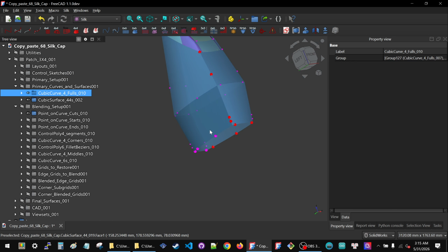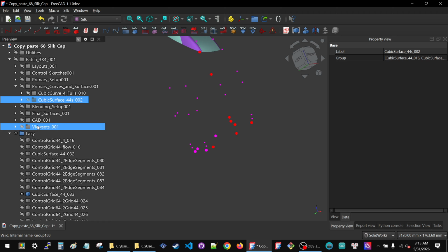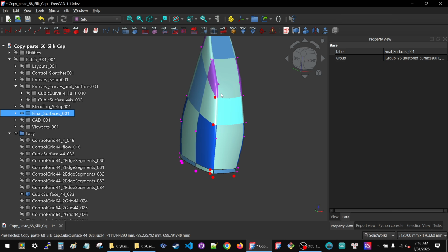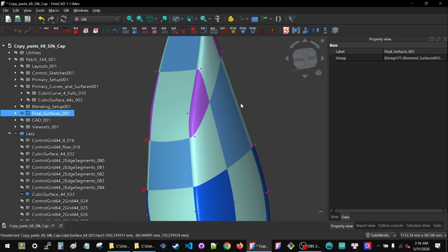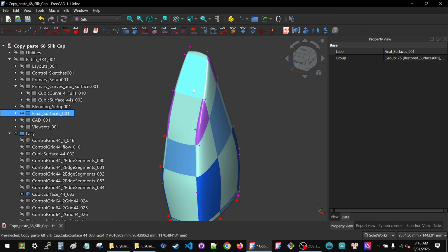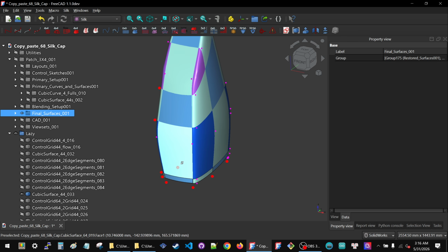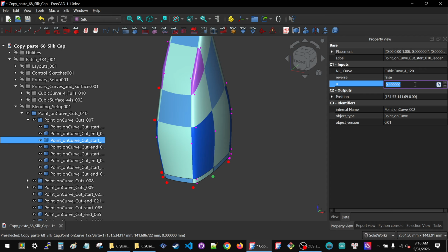Let's go here. Hide the full surfaces. Hide the curves. Show the final surfaces. And everything has snapped back. Because we added this surface at the top here, we have to force the opposite sides of our loft to follow each other. Remember, I intend to eliminate that restriction, but that's the restriction right now. Let's go this one to 0.1, F5. So now we're going to have everything at 0.1, 0.9.